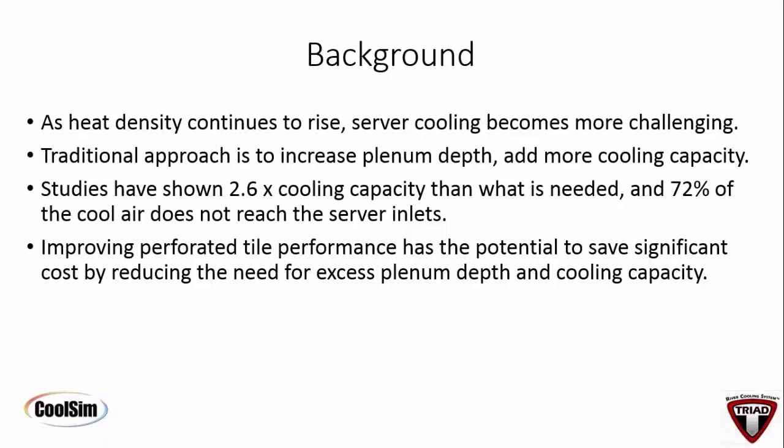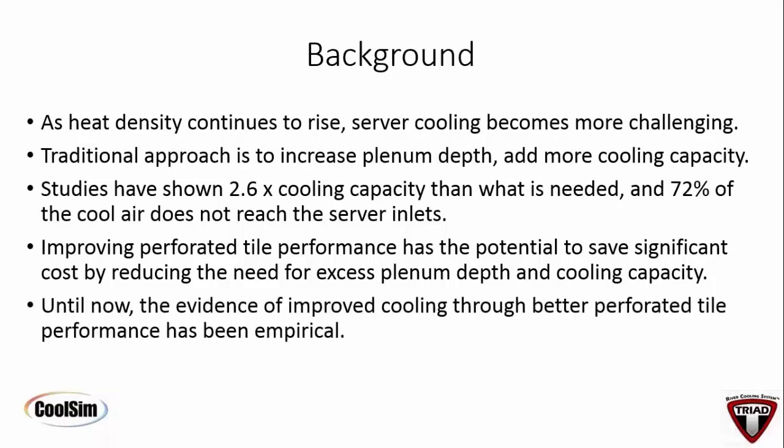And one of the fundamental ways to do that for raised floor data centers is to change the perforated tile. Take a look at what you can do in the tile area, because relatively speaking it's low cost compared to the cost of a cooling unit or the cost of adding extra capacity of one kind or another. Putting tiles in the floor, particularly for raised floor data centers, which is what we're talking about here, is a lot cheaper than anything else.